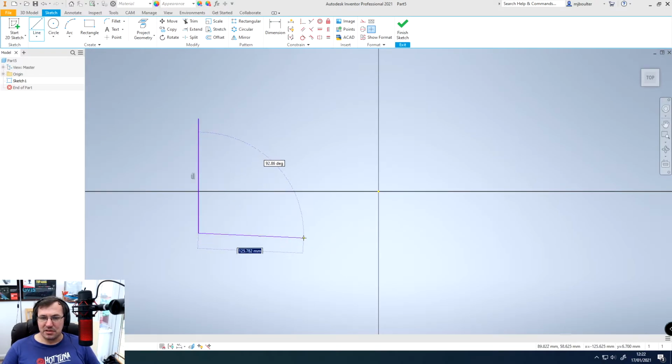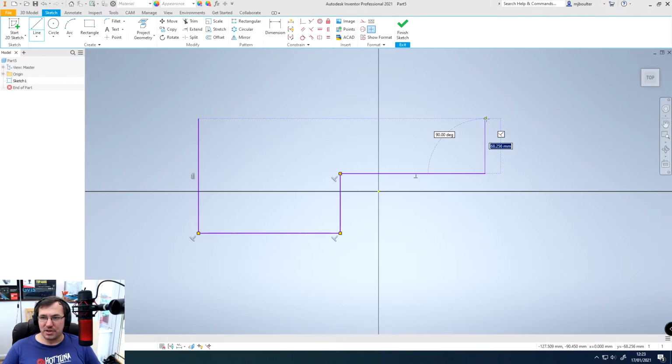Once you've completed, then it will give you another line that you can draw again, and it will snap to our horizontal or our vertical, depending on if that's what you want, or it will just go to any angle at any length. So we'll snap to our 90 degree, and we'll just continue some sort of random shape. Now we have this predictive mode as well, so you can see here it's predicting that we might want to complete this shape, and it gives us this dotted line to show that we're at exactly the same height as the line on the left hand side.